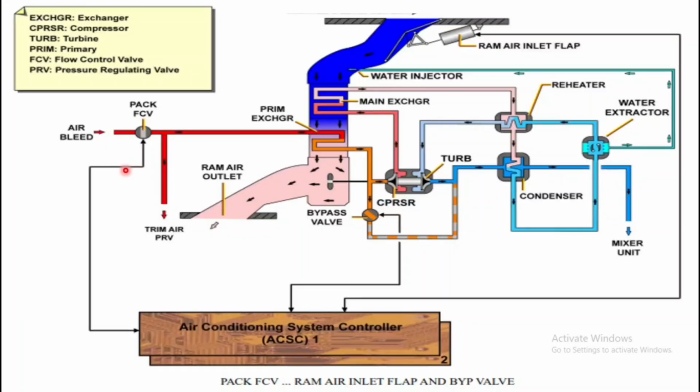The FCV valve will close automatically in case of pack overheat on ground. If there is an overheat warning, automatically this FCV valve will close. On ground only, during engine start, the FCV valve will close. On operation of the fire or ditching push button, this FCV valve will close. So many interlinks with the system. We are going into deep knowledge, so it is better to understand all the components. This will boost your knowledge. All are controlled from the air conditioning panel, which we will discuss in the last slide.